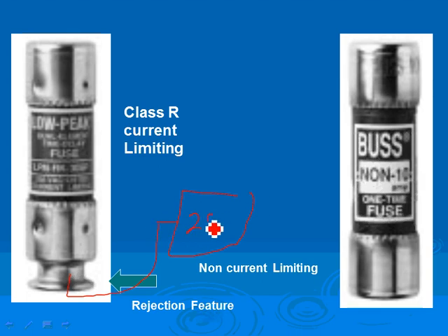This is rated for a 25K withstand rating, okay? And right here at the load side, I did the short circuit calculation and came up with 35 kiloamps. Now as the current goes through the circuit and the fuse, guys, it will open so fast, within a quarter of a cycle, that the 35 will never be seen by this equipment.